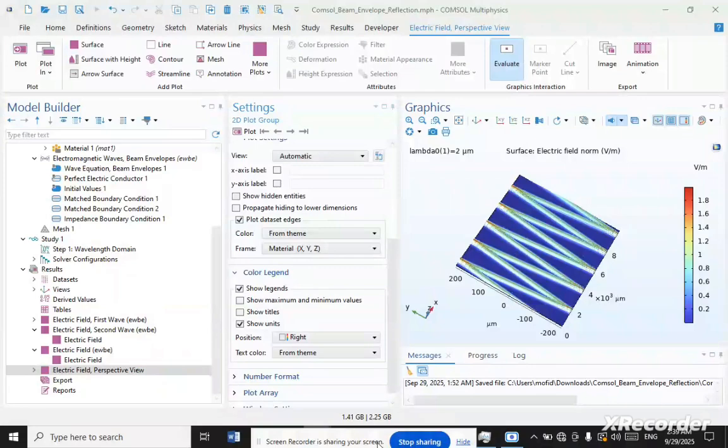The next one is meshing. This approach allows for a much coarser mesh in the direction of propagation because it only needs to resolve the variations in the envelope, not the full wavelength variations of the total field. When to use it? The first one is waveguides and optical devices, ideal for simulating devices where light travels in a known direction.